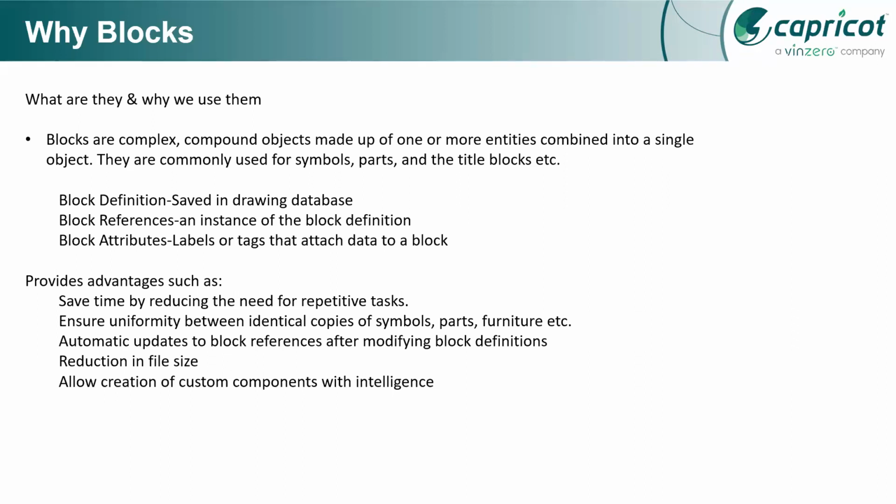The advantage here is that, let's say it is a repetitive task, which would otherwise be a very time-consuming process where you have to copy all those elements multiple times. A block is the best solution, where you make identical copies. Once you change something inside the block editor, it is applied throughout your whole drawing. So the modification process is very easy.